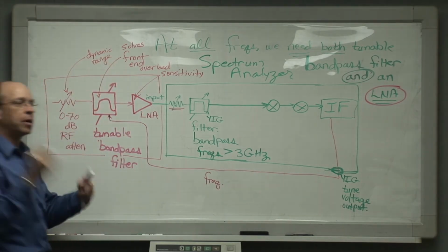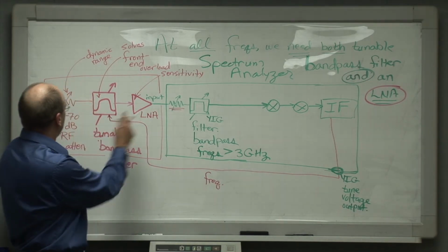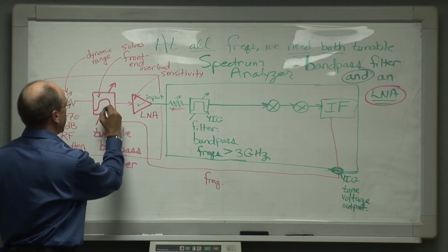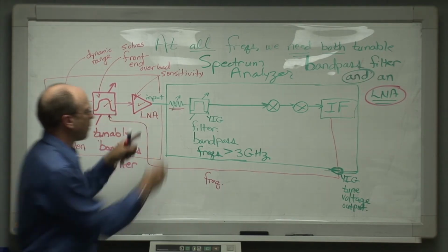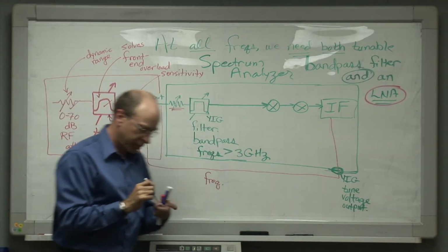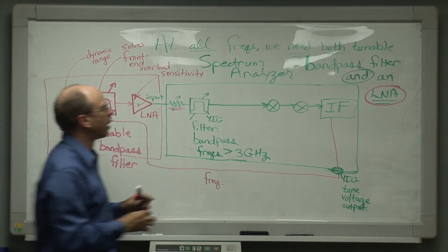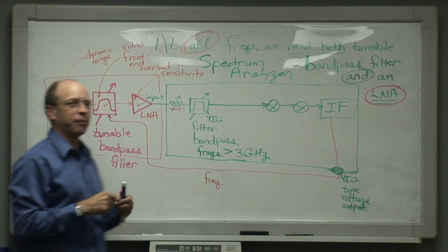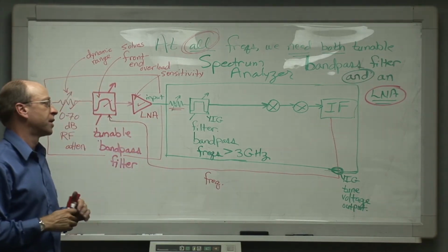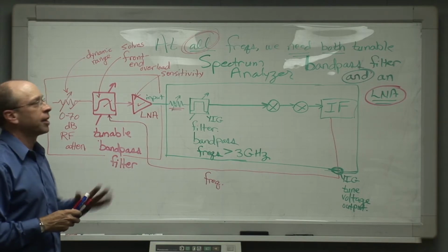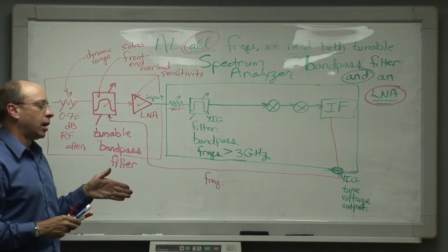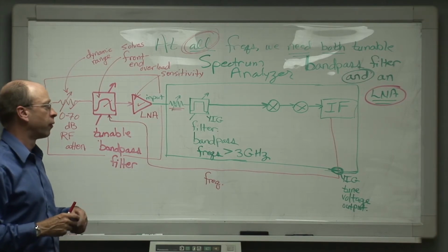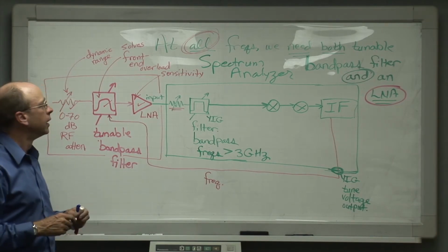But we've had to build them all into our own box because you don't simultaneously get all 3 of these components operating together the way we need them to in any spectrum analyzer design that we've seen so far at all possible frequencies across which we may be making a measurement, which for radars is going to run anywhere, putting aside the HF radars, anywhere from about 400 megahertz on up. Certainly all the way from 400 megahertz up to 18 gigahertz.